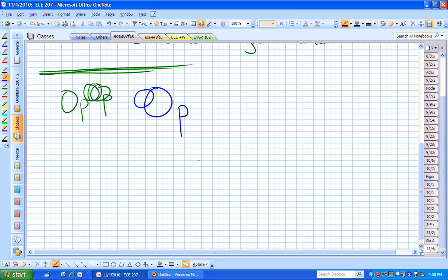I don't understand why we can assume IX and IY are both 0. That's the property of this operational amplifier. Remember our original ideal operational amplifier concept, and that was that the inputs, where are they going?